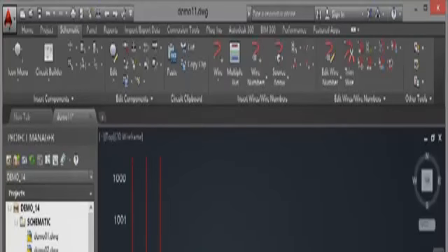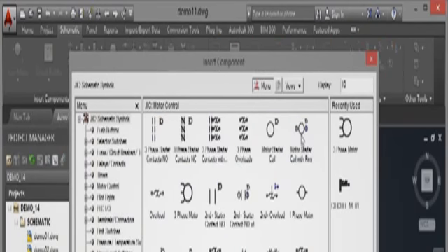When I click on OK, it's automatically inserted that three-phase motor, because it knows that this is a three-phase multiple bus piece of wiring. Other sorts of components I can add are things like contacts, switches, but I've got a whole load of three-phase schematic components that I can add to a drawing. So if we go back to the icon menu again, and I go back to my motor control, I've got a three-phase starter contacts normally open, a three-phase starter contacts normally closed, and so on and so forth.